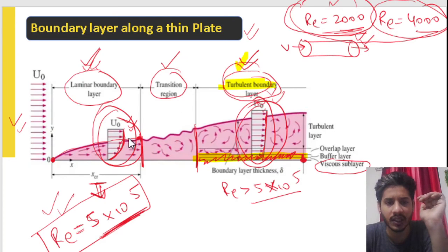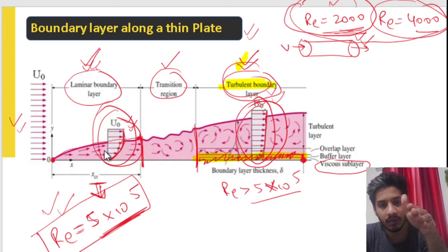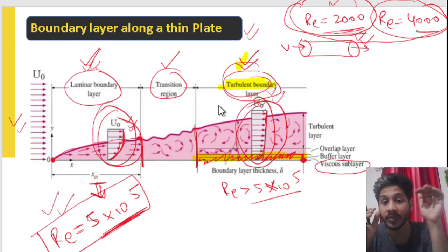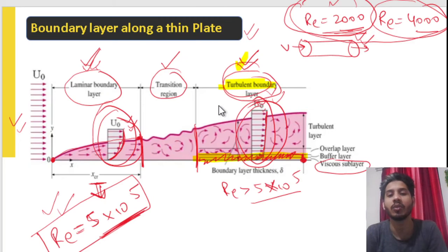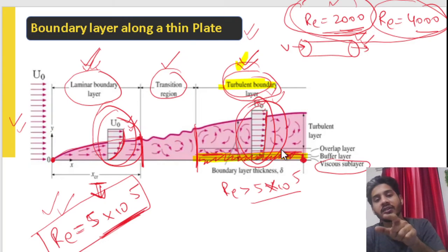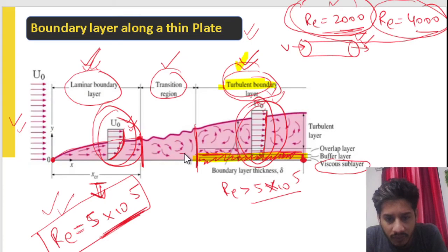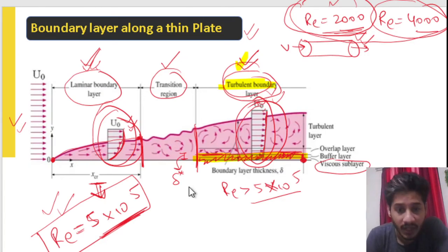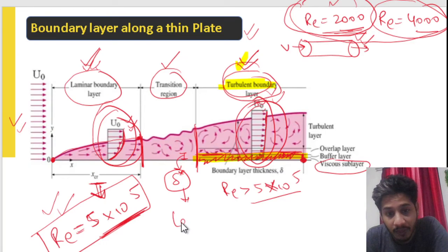All right, this is clear. We started from a laminar flow, then there is transition, then obviously turbulent flow. In turbulent flow, the flow is very haphazard and the fluid is behaving very aggressively. But within the turbulent boundary layer, there is a small region where we can consider the fluid to be still laminar. But this is a very small region, up to this very small height, and this layer is basically the laminar sublayer. Please do remember this.